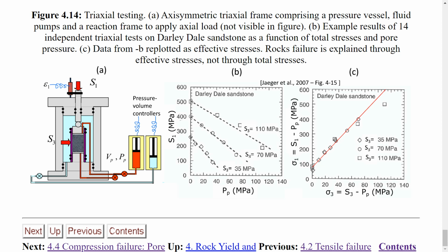So by injecting fluids, for example in hydraulic fracturing, we can increase pore pressure enough so that the rock becomes weaker. By increasing the pore pressure, we can help the rock to fail in shear, because we are decreasing the frictional strength by relieving that stress in the other direction. So sometimes we could just fail rocks by increasing the pore pressure.